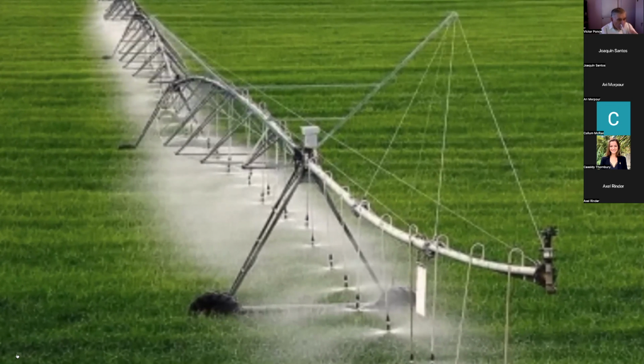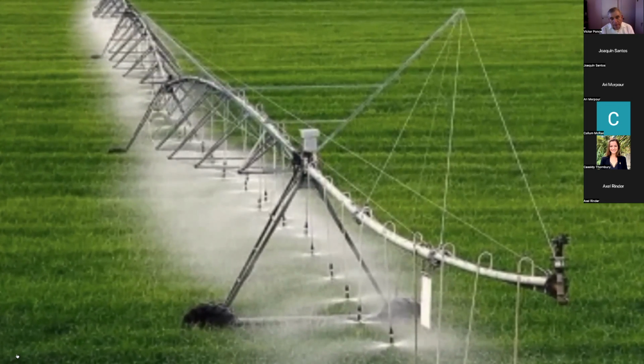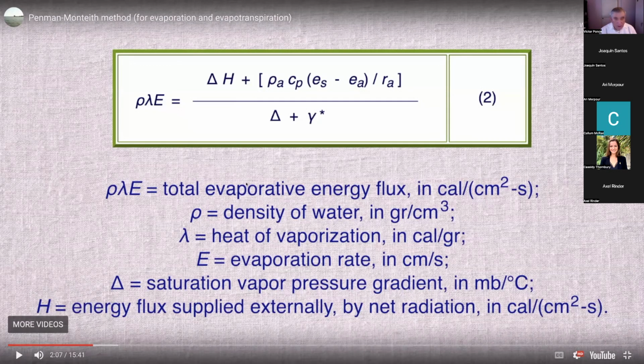The original form of the Penman-Monteith equation in dimensionally consistent units is the following. Notice that in here we in fact have a Dalton type, but Dalton did not put in there rho sub A, C sub P, and R sub A. That's the difference.